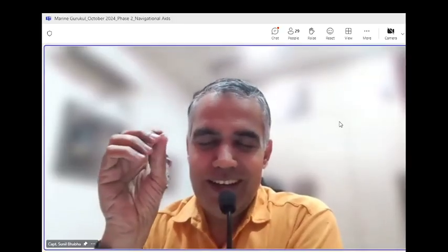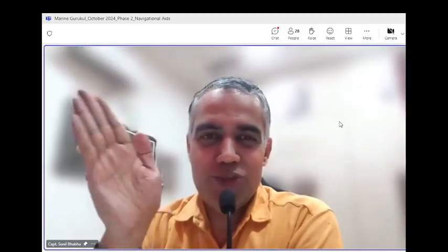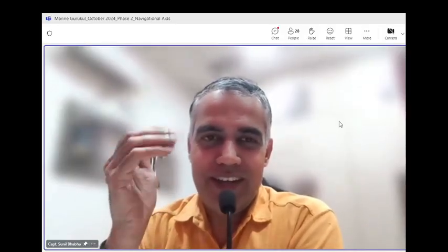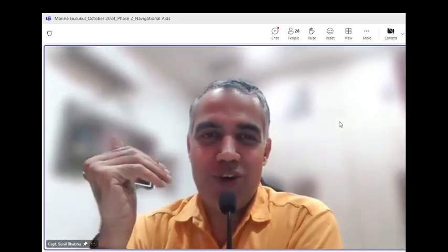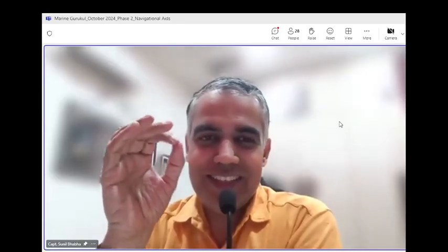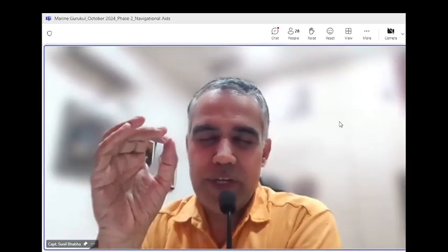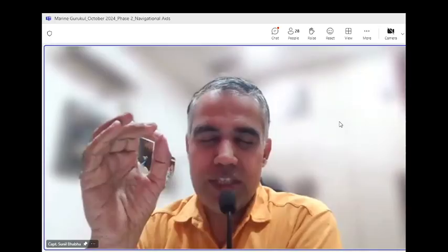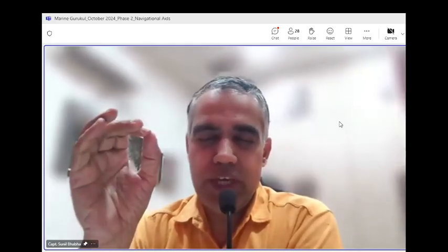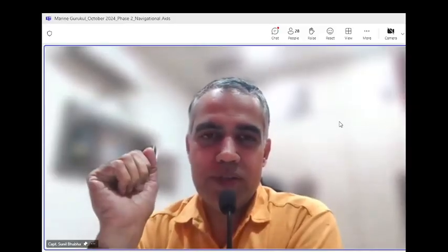Okay beta. The things you are doubtful about, one is the bearing opening up or closing in, another is the range increasing or decreasing, leave those out. And the standard items: what is the course of the target, what is the speed of the target, what is the CPA, what is the TCPA, and what is the aspect. These are the standard items which we report.